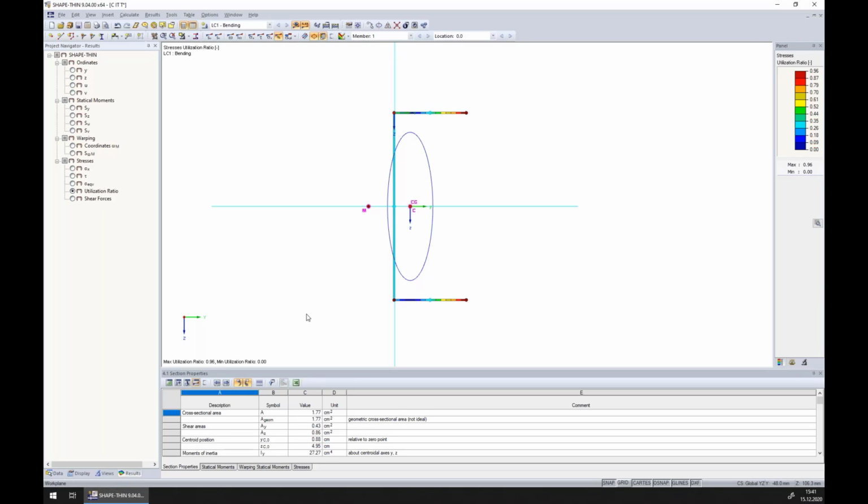But anyway, the issue appears that we have no feedback if the cross section will buckle. If we imagine that this cross section has only a thickness of 0.1 millimeter, so we can change it infinitely. And therefore, I apply a second method, the standard Eurocode 3 method.